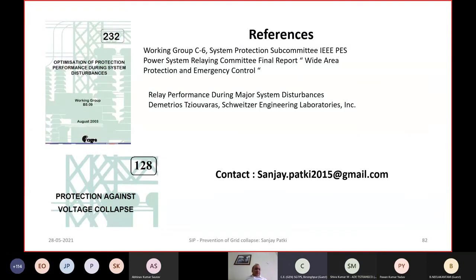Yeah, it is safe to actually consider the bus bar source as an infinite bus bar. What you are saying, zero source impedance, is like an infinite bus bar. Right. So that is very safe, but then you will be slightly overprotective and sacrificing on the sensitivity, because the voltage setting will go a little higher, and the higher the voltage setting, the lesser your sensitivity of coverage of the winding to that extent.